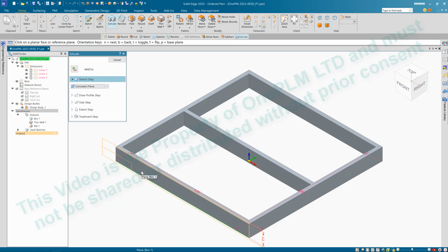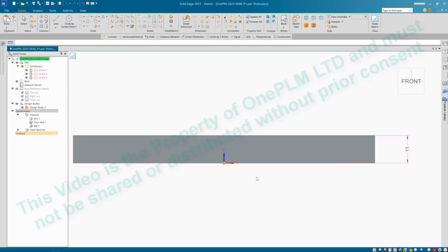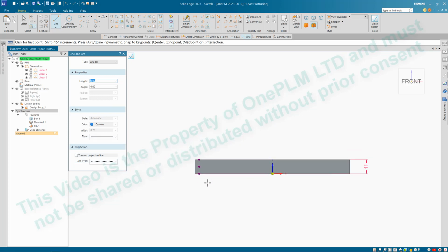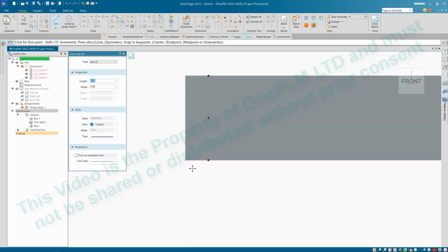Notice we've got a green edge at the bottom, that is the bottom of our sheet, so we need to make sure when we click on there we've got that correct edge. It tells us shortcuts at the top in this little prompt bar telling us how to do it, but as long as we're following this, we should get this okay. Once we've done that, we're going to get our view. What we need to do is just use the scroll wheel, zoom out, move our mouse towards the left hand side, and then zoom back in on there.